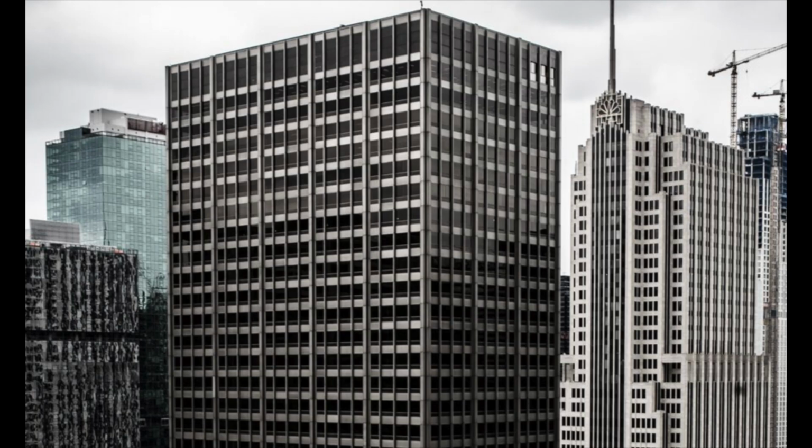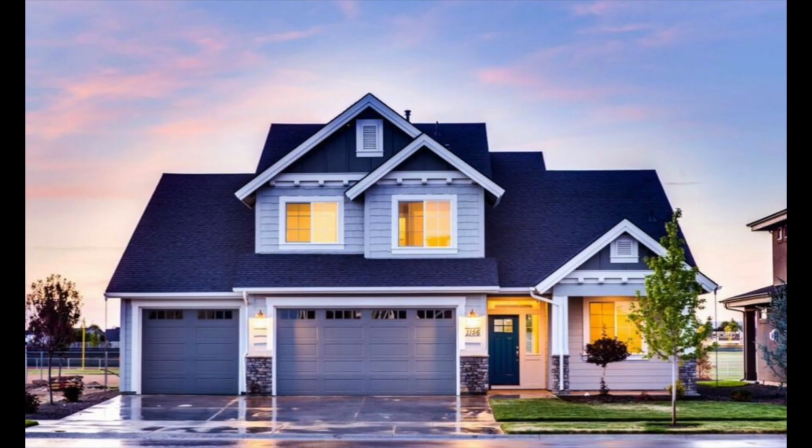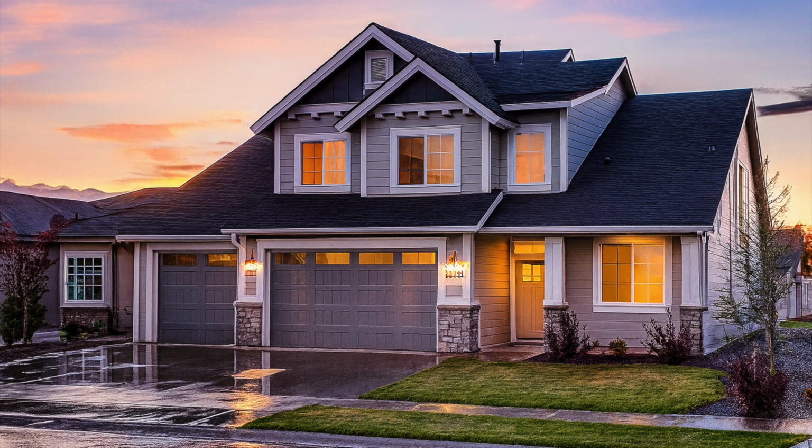Also known as a three-quarter view, an axonometric view of an object is essentially a 3D depiction on a 2D drawing. Take our elevation example from the previous section. Once standing directly in front of your house, looking at the front door, take a walk to either side until you're oriented approximately 45 degrees from the front door, rather than perpendicular. You'll still be able to see the front of the house, but you'll also have a view from the side.